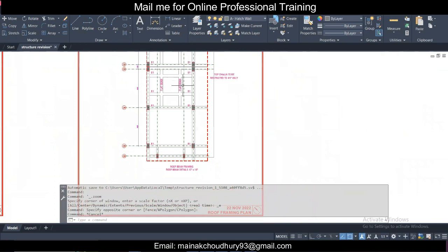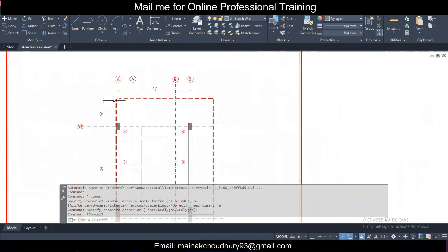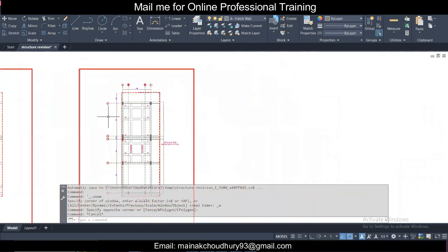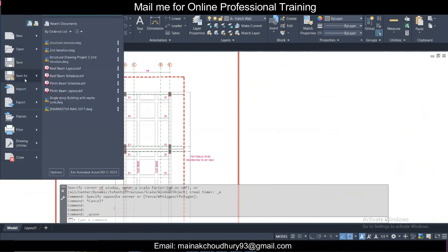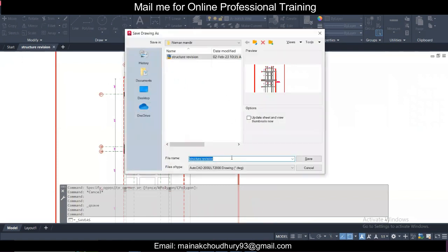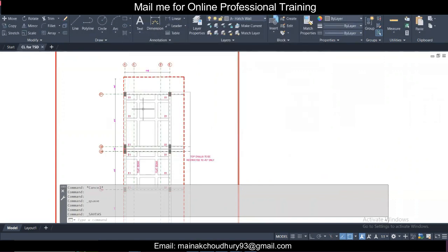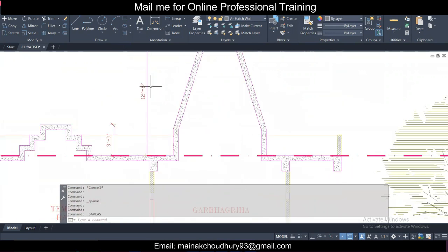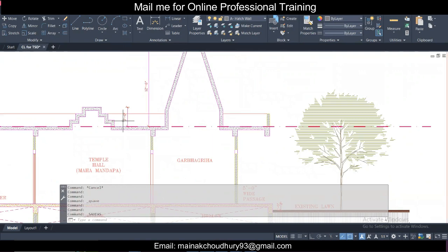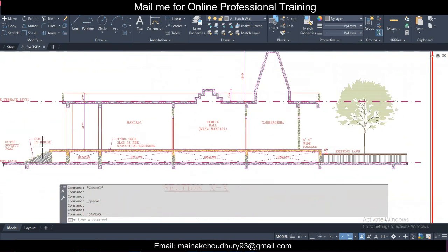So yeah, this is in DWG. Tekla does have a way of importing the center line in DXF. So I think I don't have to worry about that. First of all I'll save this file, and I'll make another copy of this file. I'll do save as, and this will be CL for TSD. TSD is the short form for Tekla Structural Designer. I always save in AutoCAD 2000 format, so that everyone can access my drawing whenever required. Okay, this is also there. It's 12 feet 6 inches, 3 feet, 3 feet here. Okay, this elevation is also there.